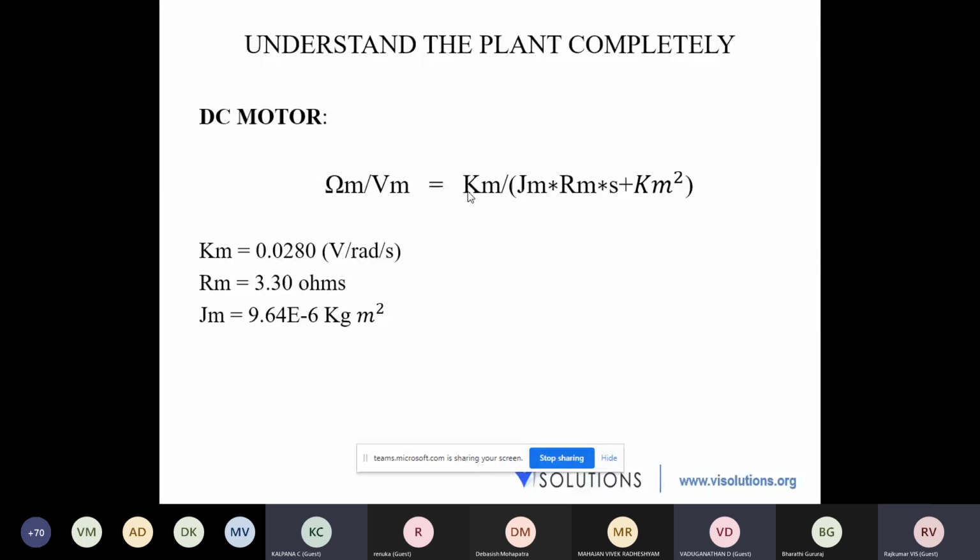In order to do that, ideally we need an actual DC motor and actual motor drivers. To control that motor, we need a microprocessor or microcontroller to control the motor driver, which in turn converts the commands we give into electrical output. That electrical output is given to the motor, and depending on the command we give, it rotates at that particular speed. And depending on whether it's open loop or closed loop, we'll get the feedback as well.